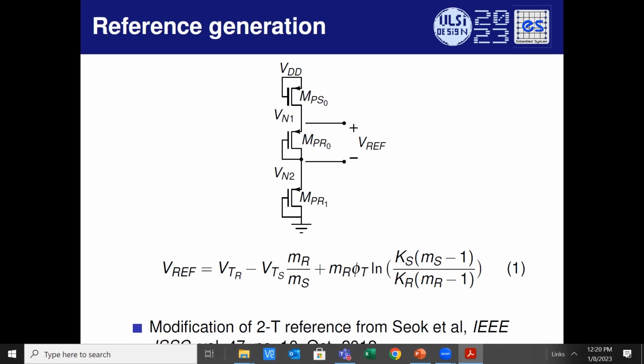So going back again. When you talk about the PMIC, power management IC, it has lots of other modules such as LDO. So how do we integrate this band gap reference along with them? We'll see, LDO is just another application. I'm just picking up one particular application, an under voltage lockout circuit.